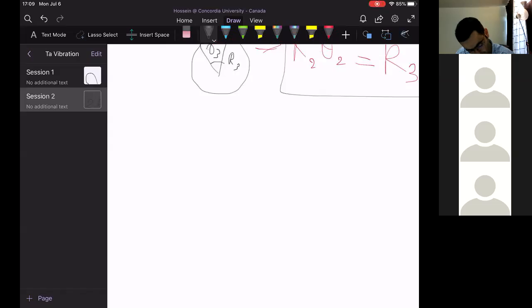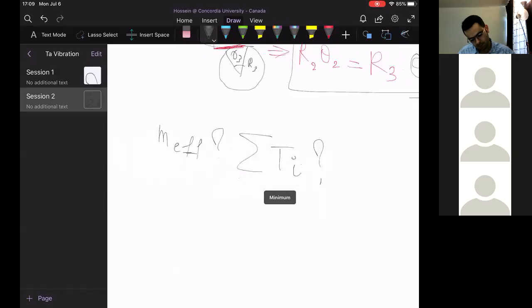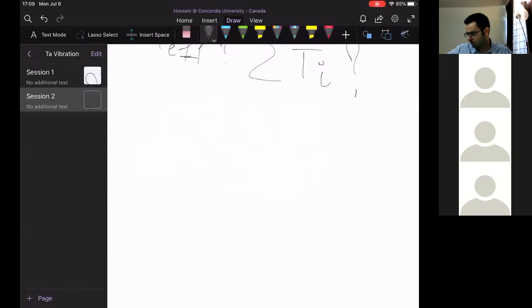Let's go for calculating effective mass. You have to calculate all the kinetic energy of the system. We have a linear motion for the mass m, so 1/2 m x dot squared is the kinetic energy.